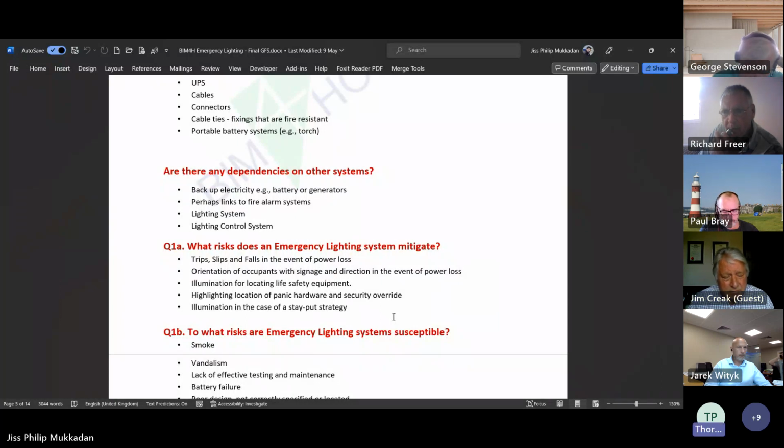Well, it's still dependent on a light source. Well, the emergency lighting is dependent on electricity. Emergency lighting is dependent on there not being any smoke. So we can go round and round in circles, but you can't single photoluminescence out, because it's excited by daylight. So it's an anathema to separate it as needing something when it doesn't. All signing requires illumination. Most emergency lighting signs today are externally illuminated, not internally illuminated. So the same thing applies. As soon as you externally illuminate a sign, it's got a dependency.